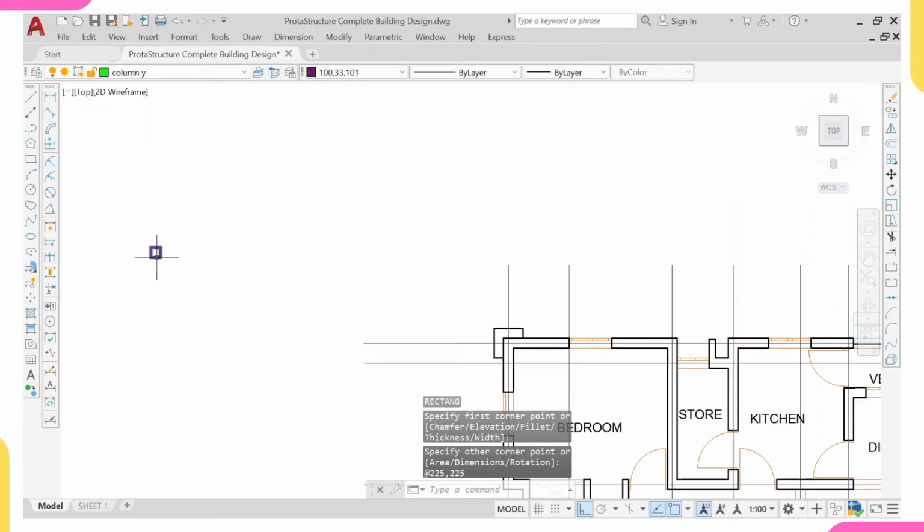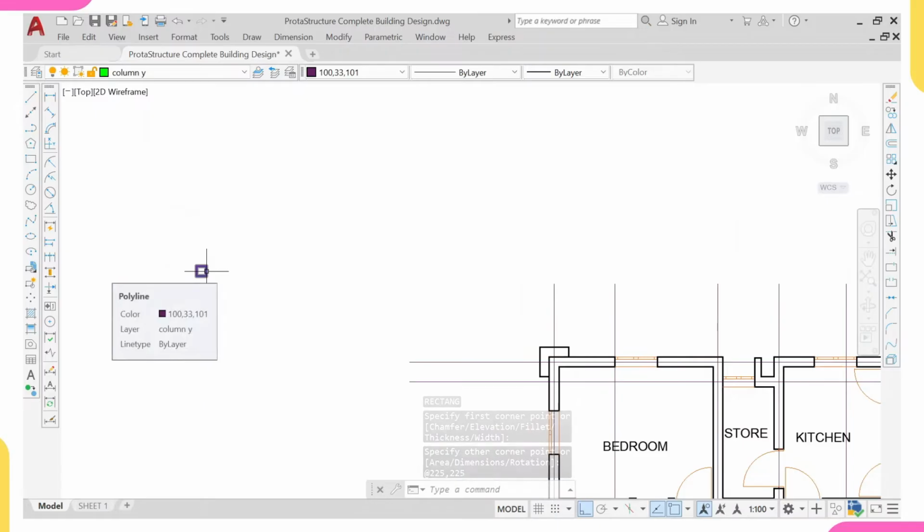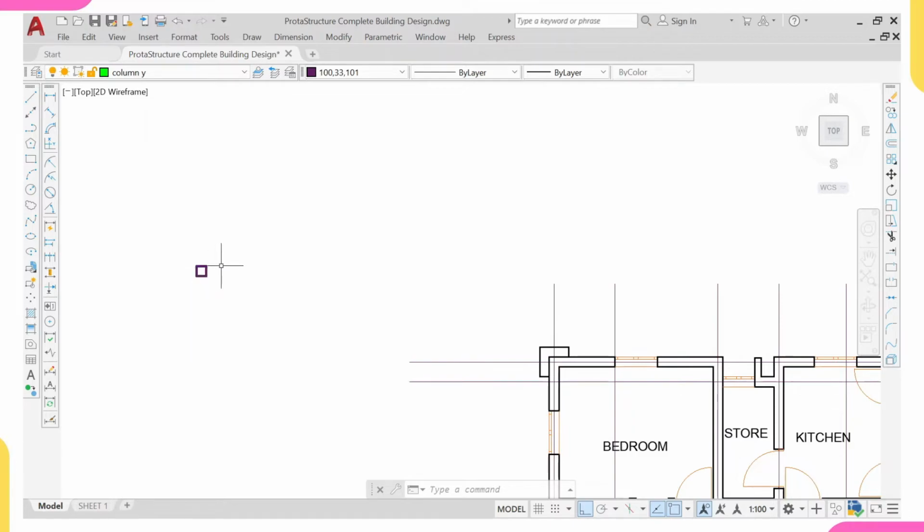Yeah. So since I've gotten this, let me also say something. Column placement is solely dependent on the engineer. Yes, my column placement can differ from your column placement. But the thing is that the engineer needs to follow the governing principles in column placement in order to place his column well. Because once it comes to structural design, two things are of necessity to us. First, safety. Second, economy. If your building is safe but it is not economical, you are not a good structural engineer. But safety is our priority.